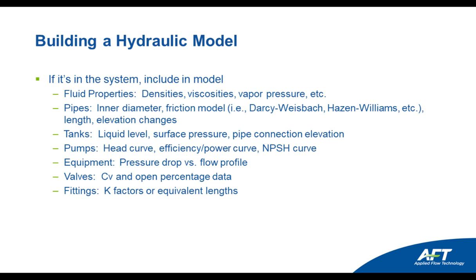And so if you absolutely ensure that all of the diameters in your flow model are correct, and maybe your pipe lengths might be off a little bit here and there just due to not detailing down to the 16th of an inch, you could still have a decently accurate flow model. So be sure to keep that in mind.